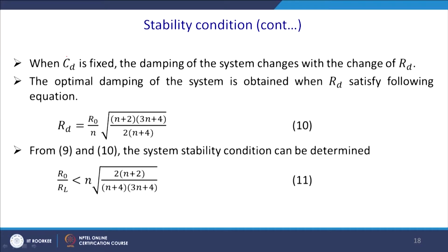You fix the C d, because generally C d comes in some standard values, for example 47 microfarad or some other values. Once you fix the value of C d, you get a range of R d.